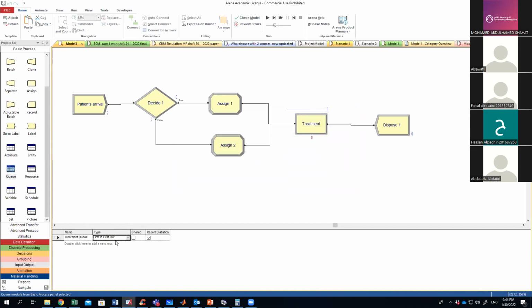So when you go to the queue, you can say you will take the highest or the lowest attribute value. If you want to give priority to the critical, you should choose the highest attribute value, and we choose the attribute which is priority. So look at the sticker called priority on that entity. If the priority is higher, this entity will come to the front of the queue. If the priority is lower, that entity will go to the back.